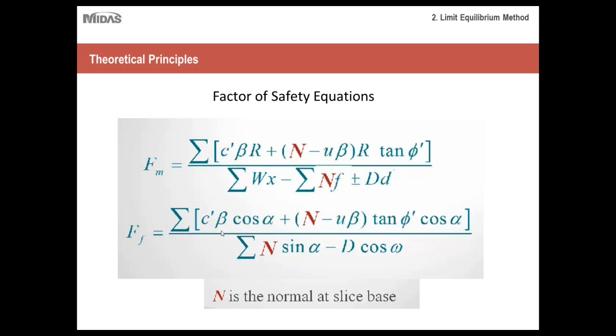And just as a recap, I'm sure you're all familiar with what the factor of safety is, but just to reiterate, the factor of safety is essentially a ratio of the forces that are keeping the slope stable versus the forces that are acting against the slope, pushing against it to maybe cause it to fail. Usually a minimum factor of safety for most cases would be about 1.5. In other words, for every 1 Newton of force acting against the slope, causing it to be unstable, you'd have 1.5 newtons of force keeping it stable. So the higher your factor of safety, the more stable your slope is.